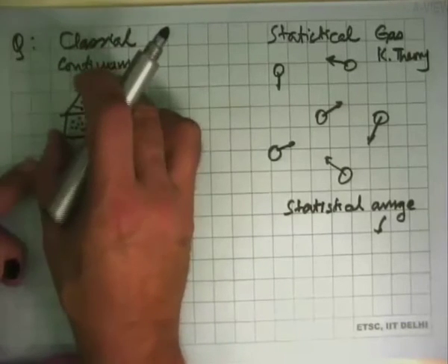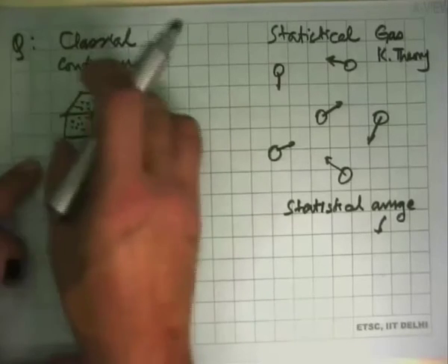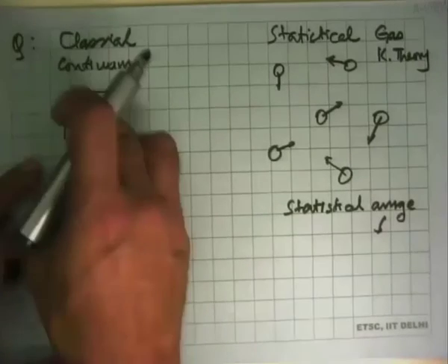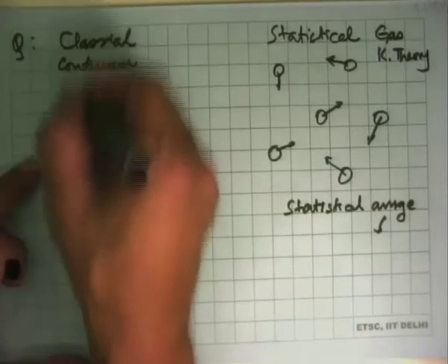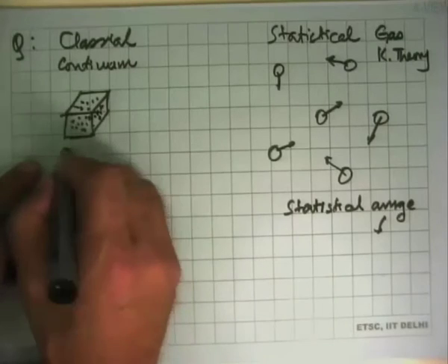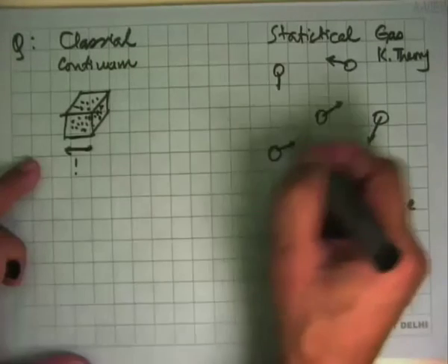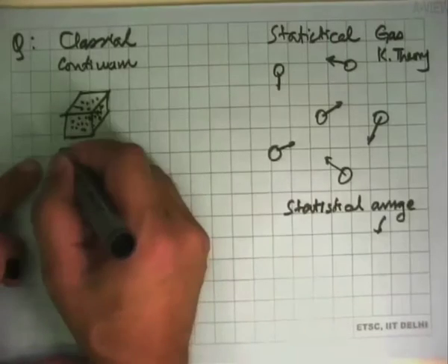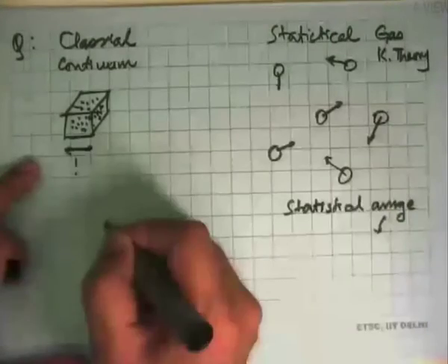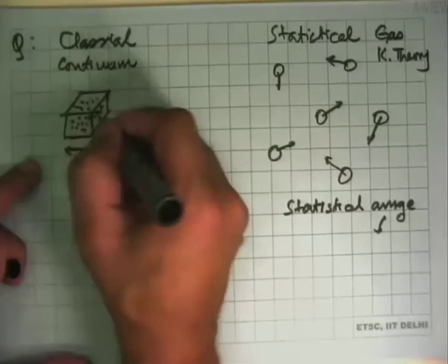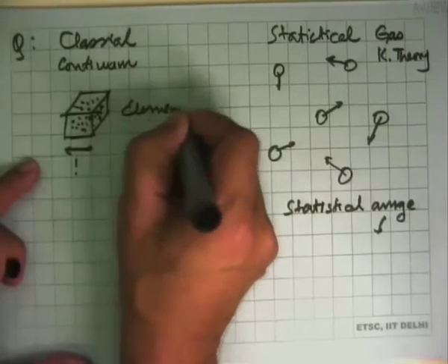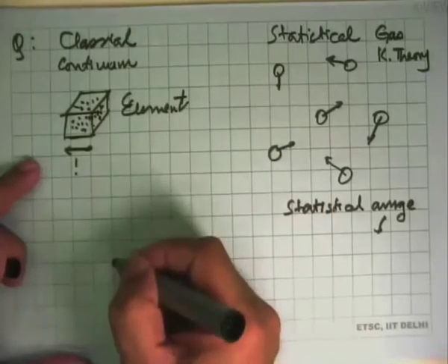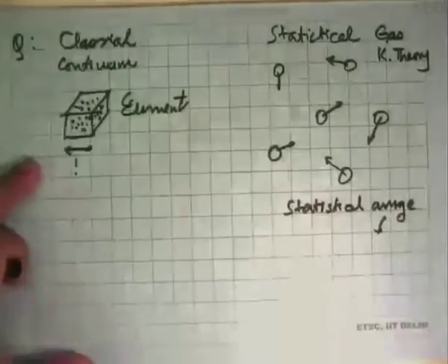So whether it is pressure, temperature, or enthalpy, we can get all of that from an average, and we will not worry about where that average came from. We start off by saying that this is the smallest element we have, some size we can put on it. The intermolecular distance is of the order of angstroms, a fraction of an angstrom, and this element is much bigger, 100 times bigger than that distance. We take all of these in an element, take the average properties of this, and start talking about all the laws and everything else that we have learned in this course.